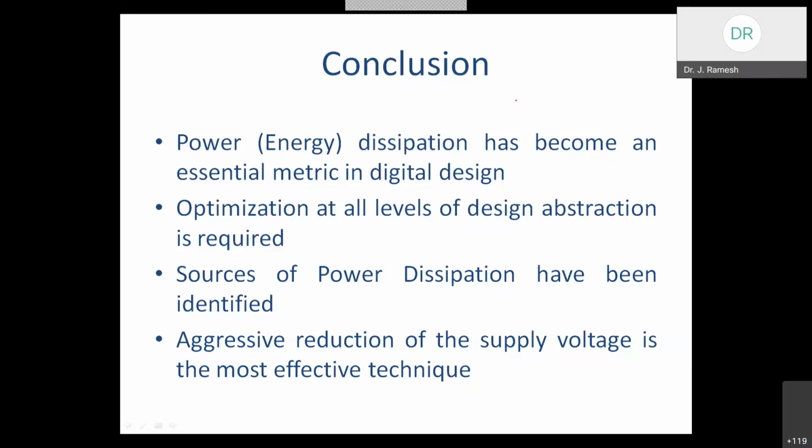Yes, madam. Nowadays we are concentrating on 5 nanometer, 7 nanometer technologies, and for those designs we are going up to 0.6 volt. But we cannot keep on reducing it, because every time we reduce the power or energy, we have to look after the delay in parallel.